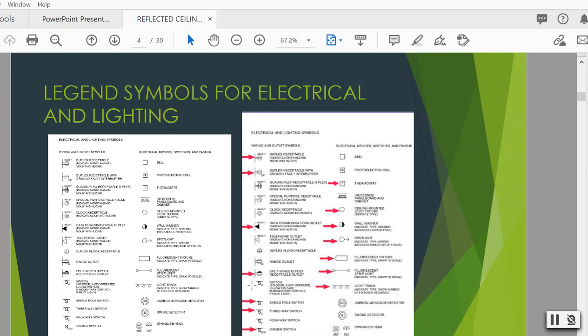Then we have our handy dandy S's. Those stand for switches, and you guys have used those. Remember, you can add things next to them. So a regular single pole switch turns the light on, turns the light off. A switch with a 3-way, we learned about that, and that turns the light on in 2 different locations. So you turn a light on at one location and turn it off at another. A 4-way we won't be using, but the next one is DM.